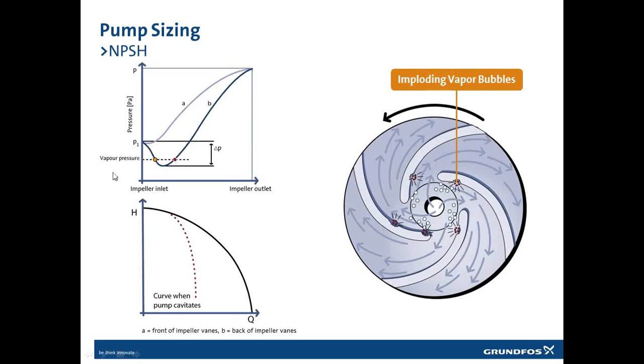Okay, we could then say I'll take a very sturdy impeller. It can withstand some cavitation, and I have enough material so it will probably run for a couple of years before it breaks down, and then I'll just replace it. Yeah, you can have that way of thinking, but in boiler feed I don't like it, because when we have cavitation we don't know where we are on the pump curve.